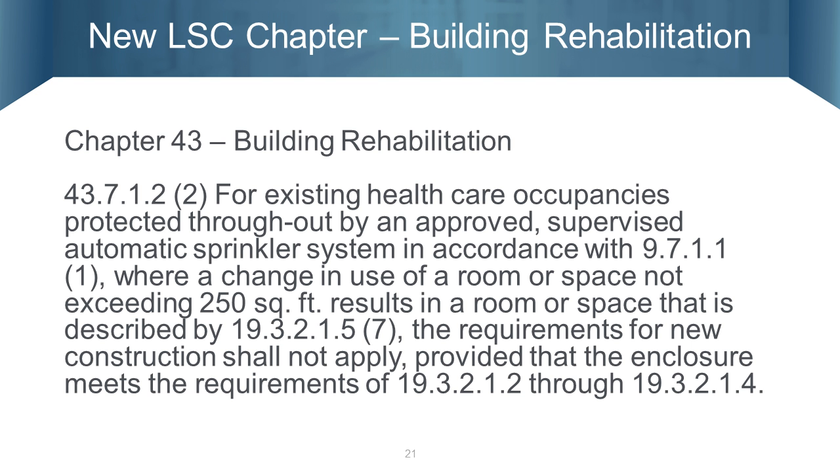What that means is if we take, for instance, a patient room and we convert it to storage, instead of being required to replace that door with a 45-minute labeled door with closer, and instead of being required to take the walls up deck to deck and rebuild them as 1-hour rated walls with 5/8-inch sheetrock on both sides, this says that even if the walls stop at the ceiling, if we're fully sprinkled, it's okay to make this change as long as we put a closer on the door.